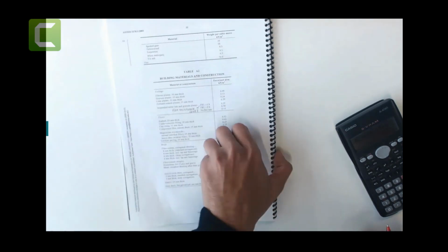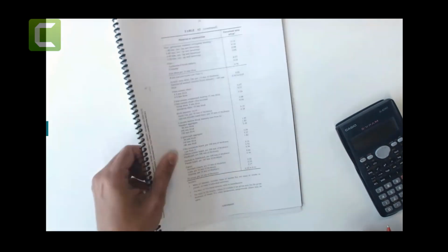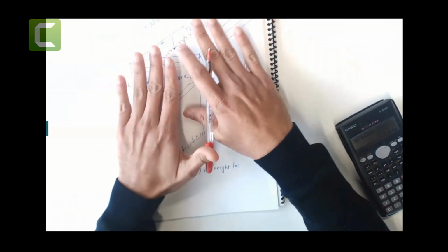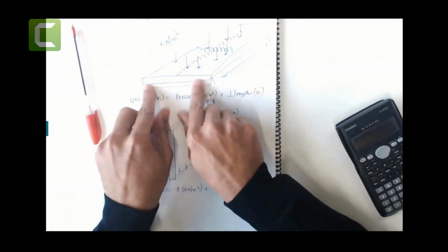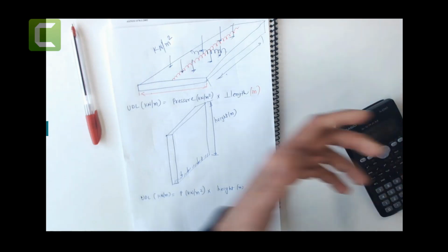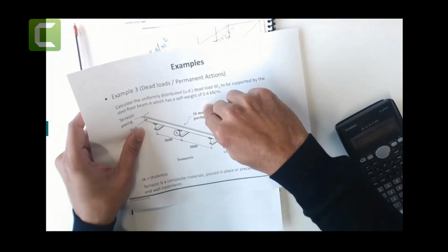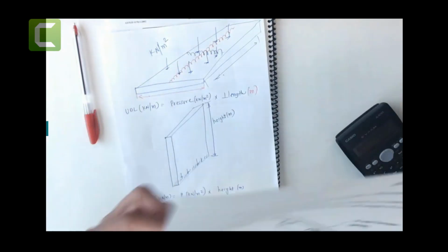So they have given you all this weight in terms of thickness, but they will give you pressures, force per unit area. If you come across pressures, in any units, and of course they have thickness, then it is pressure times perpendicular length, like we did in our examples. This paving will cause the pressure, right? And if I want to calculate the UDL load for pressures, you just multiply by the perpendicular length. So the UDL load goes this way, the perpendicular length goes across this way.